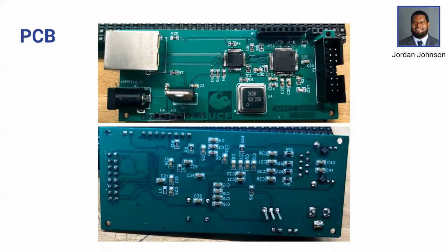Now going to the bottom of the board, I did decide to include some of the SMD components here, as it would allow us to get bypass capacitors as close as possible to their respective pins and make for a more compact design. However, I would like to mention that because I did decide to design the PCB this way, it gave some challenges with the solder mask that came with the PCB.